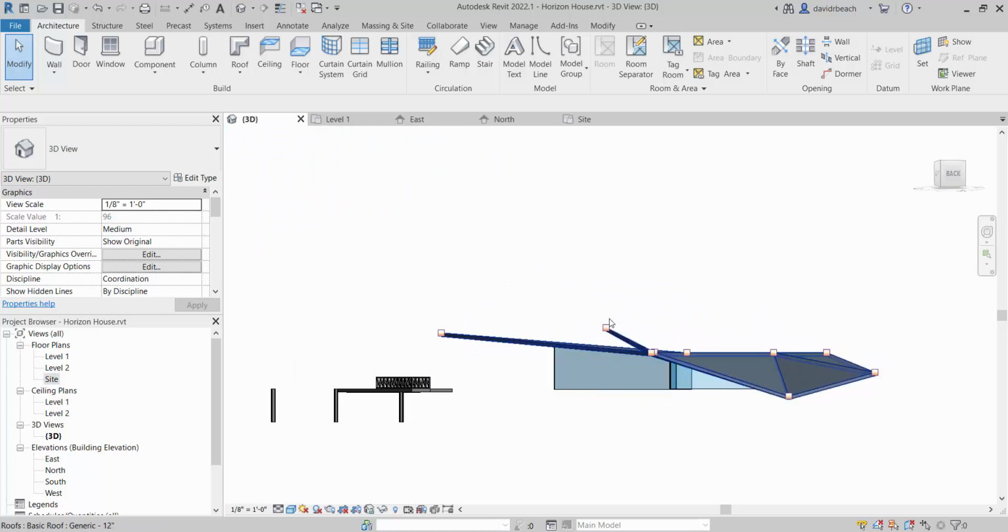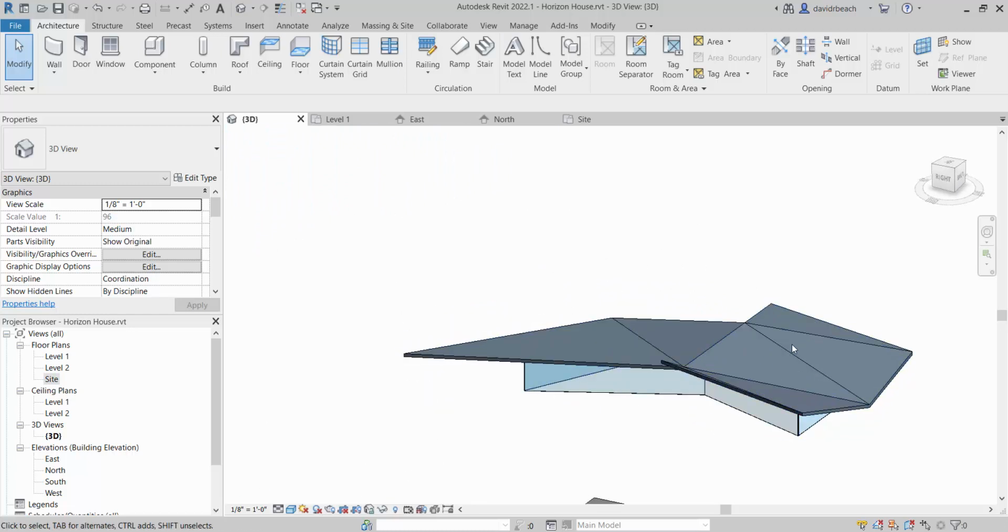Okay? Now, if I had built that roof out of, say, a custom component, I would not have had that as an option. So it knows, again, Revit has a certain intelligence to it. It knows that's a wall. Walls are often attached to roofs. I'll lock those things together for you. Right? So it's pretty quick to start building and editing up those kind of forms, those kind of components. Cool.